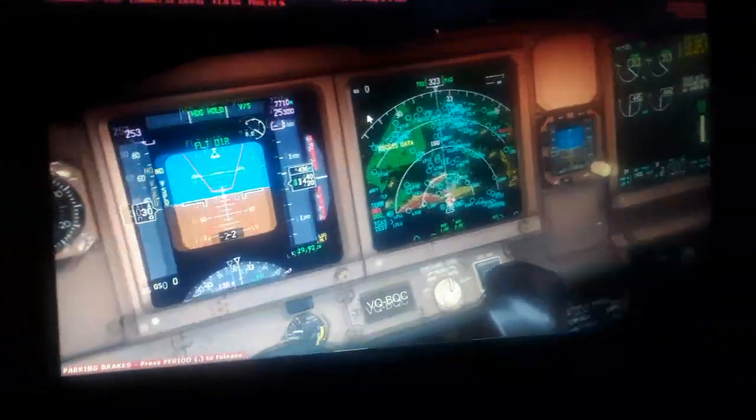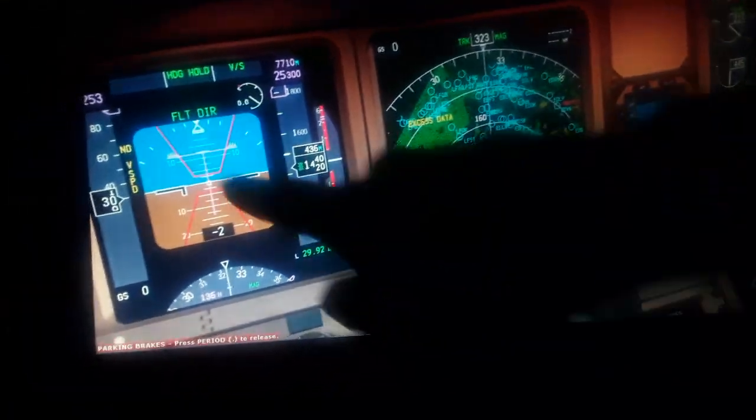Also these are the fuel cutout switches for the left and right engine, the fire extinguishers for the left and right engine, the weather and terrain radar, the radio communication panel here, and the transponder. You can change the settings for the transponder, and also test if it works, so you can see other aircraft. This generates a warning here for traffic, as you can see, and in the display.